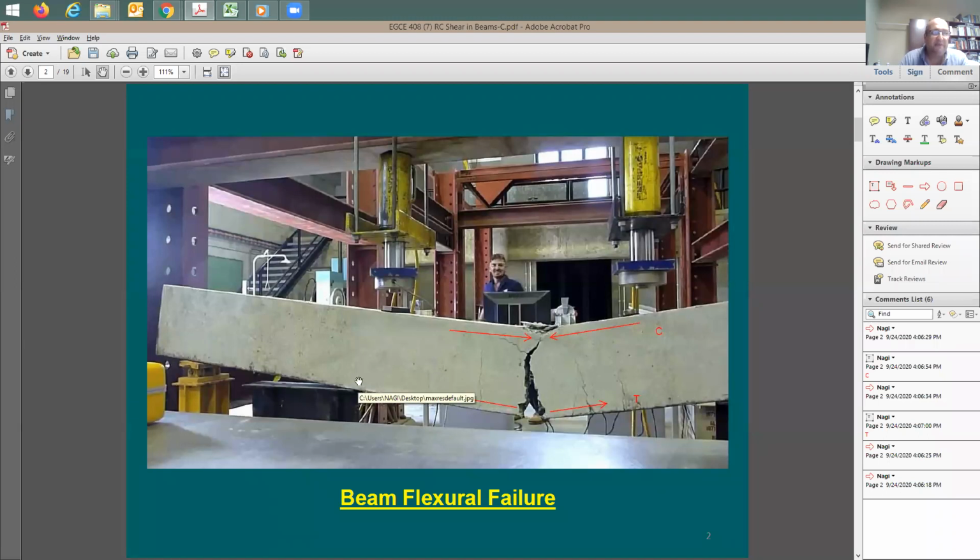Also, when you have this simply supported beam, moment on top of the support is going to be equal to 0. But when you look at the shear diagram, it's going to be the other way around. The shear is going to be max at the support, and it's going to be equal to 0 at the point of maximum moment. We understand this fact from statics and mechanics of materials. So looking at this beam, it has this moment diagram and the shear diagram at the same time.